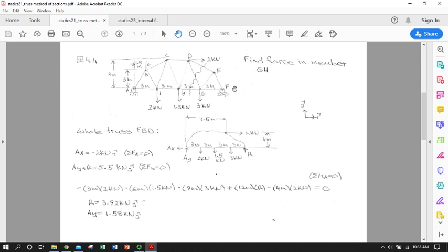There's three support reactions. Let's take a quick moment to apply what we knew about truss determinacy and rigidity before we dive in. This is an example, so we can be pretty sure that it's probably statically determinate, but you never know. You might get a colleague or a boss or an evil instructor might give you an indeterminate truss or a non-rigid truss. So now that we know the number of support reactions is 3, we should be able to say that twice the number of pins minus 3 should be the number of members. So let's do a quick count just to make sure.